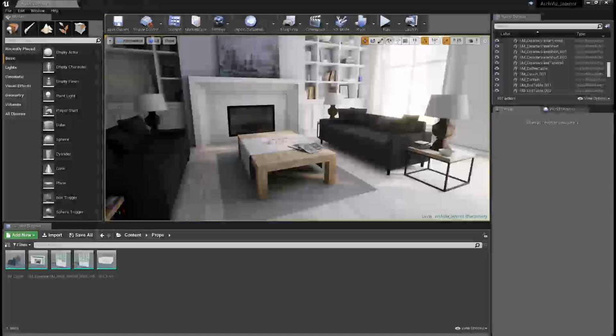Is it going to be a controlled walkthrough in which the viewer simply watches a sequence of animated cameras? If so, you probably don't need collision detection, since the viewer won't be able to move. If, however, you want the viewer to be able to move freely around the scene, you'll need collision in order to keep them within the bounds of your creation. Collision will also help avoid the viewer being able to look through geometry into places you don't want them to see.